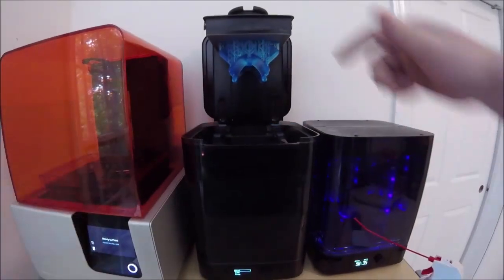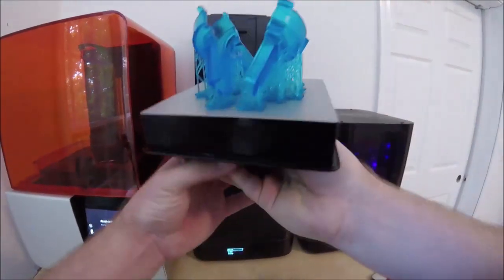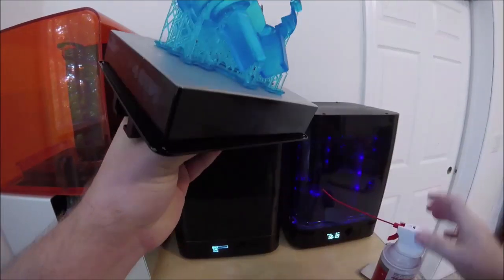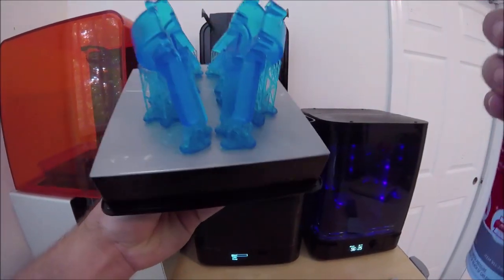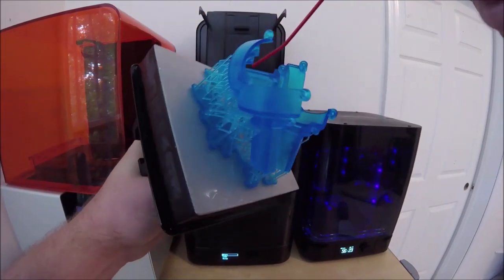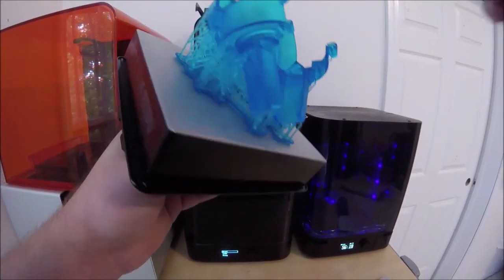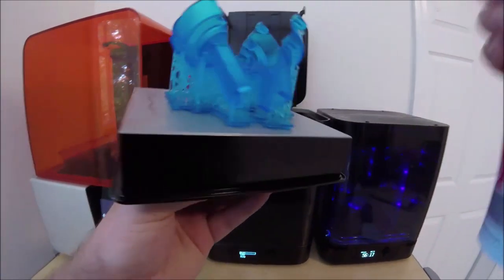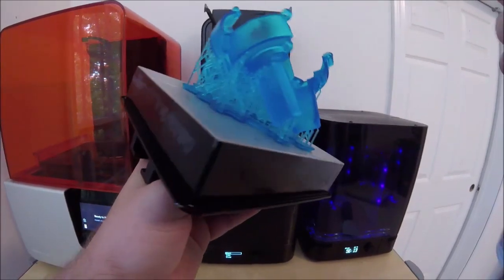Okay, so the parts have stopped dripping, and you can see they're actually starting to dry quite well. So we're going to take the build platform out and just take a look around your part. I like to see if there's any areas that might have trapped some isopropyl alcohol. Critical areas to look are usually in holes or down in little crevices. What you're going to want to do with those is make sure you blow any liquid isopropyl alcohol out of any areas where it might have gotten trapped.